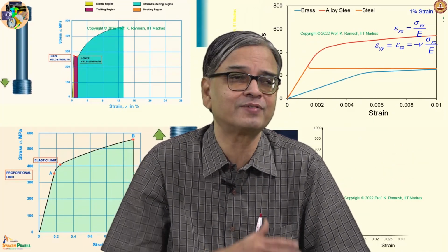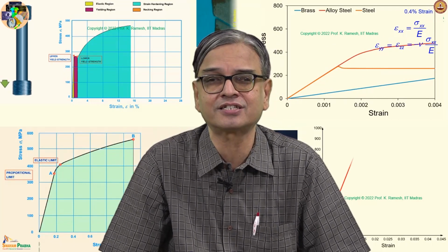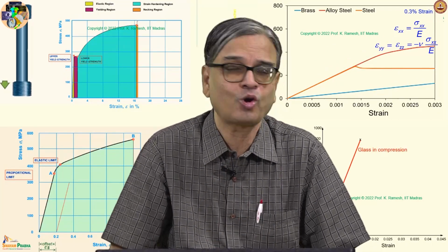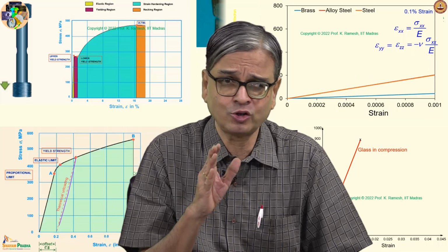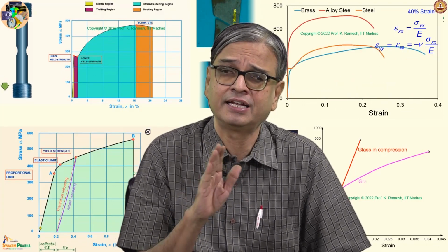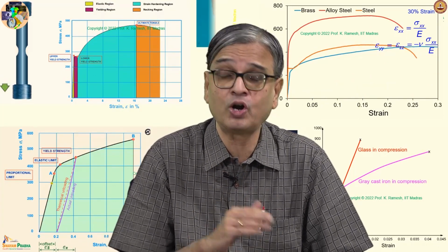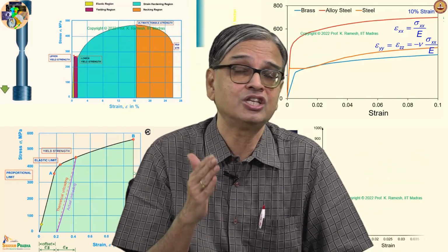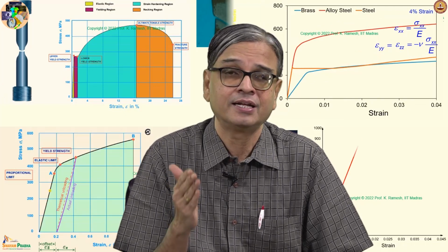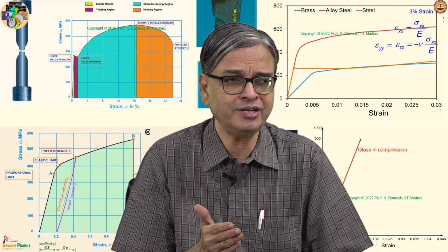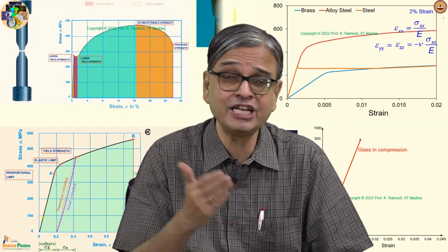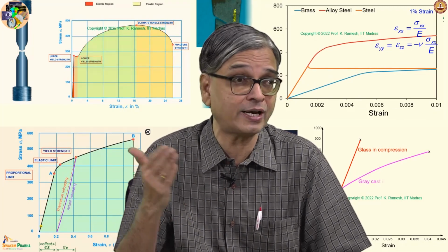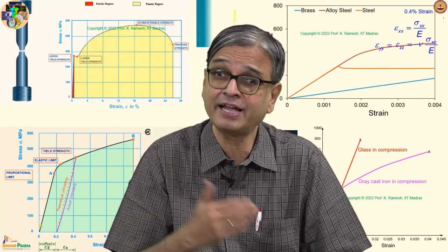So, in this class we have looked at the tension test much more closely, and I have also sensitized you on the numbers. They are very important. The important takeaway is a brittle material is very strong in compression, but very weak in tension, and the difference in yield strength can be of the order of 10 to 12 times. It can even be higher.